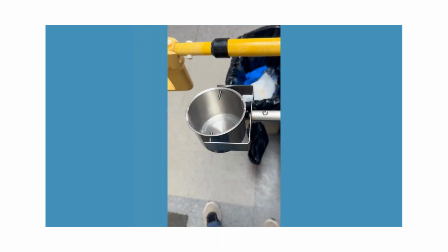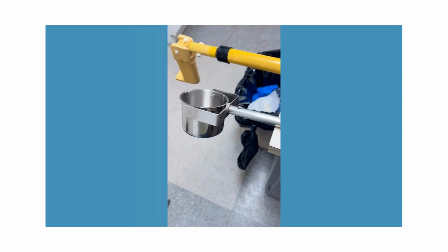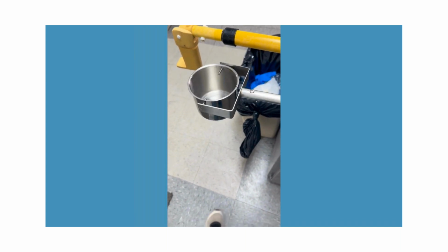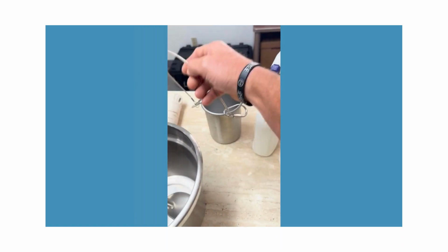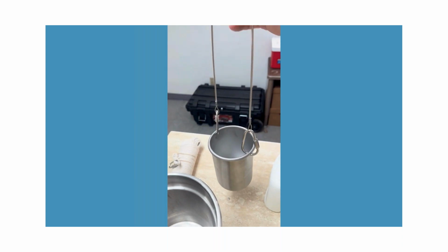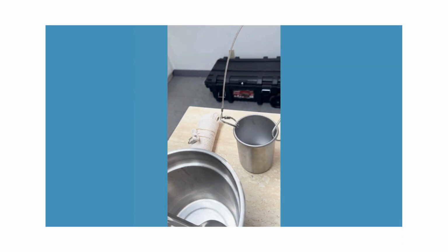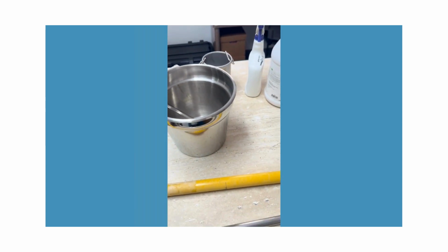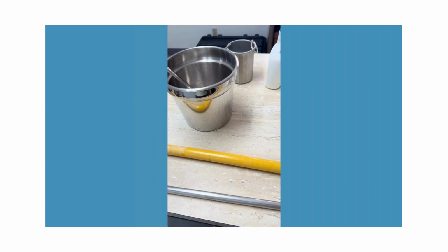If I was unable to do that, then I have a stainless steel swing arm sampler, but it's a shorter fixed handle. You can transfer the sample from this into your sample bottle, but there's always a risk, if you don't have proper decontamination, of cross-contamination. Also, for deeper wet wells, I have a stainless steel dipper bucket that I can lower down on a cotton rope and collect a sample. Ideally, you want to get your wastewater sample in the mid part of the stream of flow to ensure you get a representative sample.